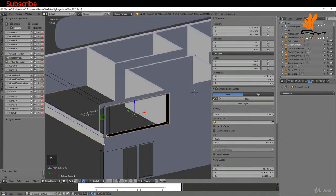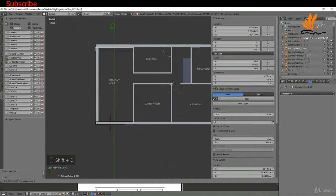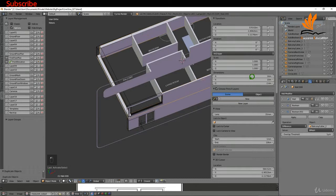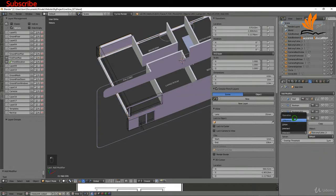And I need to make a copy of this one. So I'm going to select it, press 7, press Shift D, press Y and drag this back and just line it up in the center of that there. Over here in the outliner, I'm just going to rename this to balcony cutter 3. Press enter. And if I come back around here, I can select the wall and I can add a Boolean modifier, and again pick my balcony cutter 3 and switch it to difference.